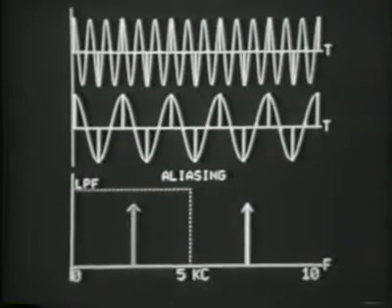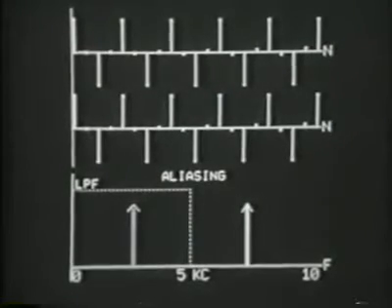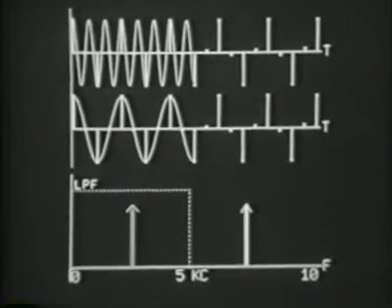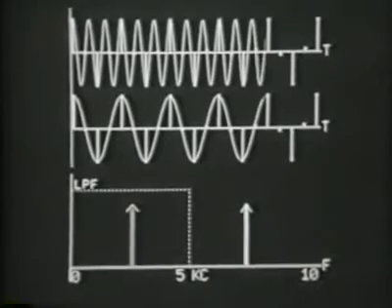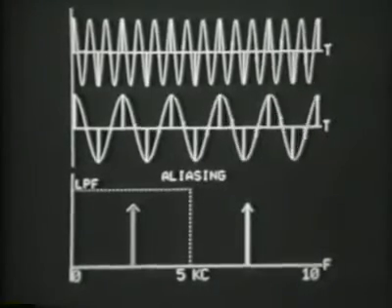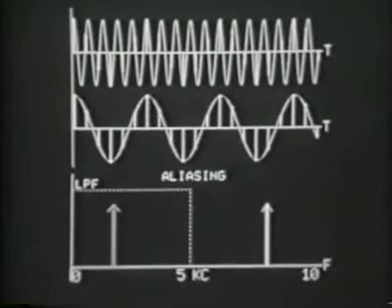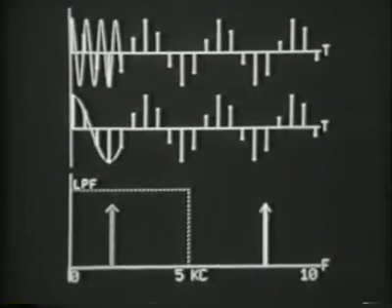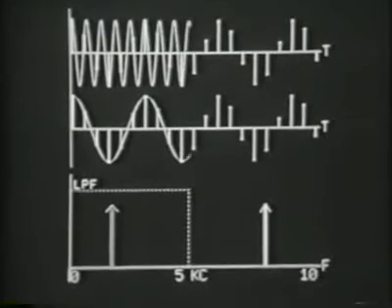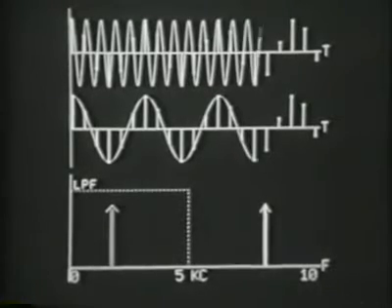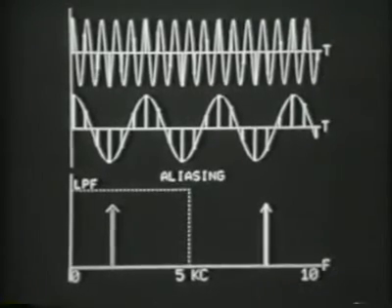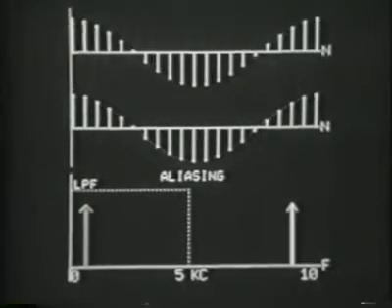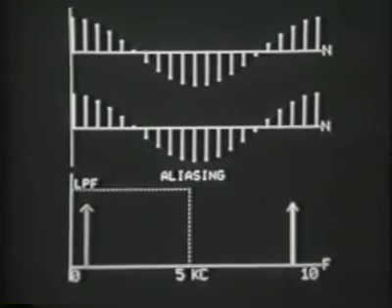But the important point is that even when we have aliasing, the samples of the reconstructed waveform are identical to the samples of the original waveform. And notice that as the input frequency increases, in fact, the interpolated output, the reconstructed output, has decreased in frequency. Now, as the input frequency begins to get closer to 10 kilohertz, in fact, your eye tends to also interpolate between the samples with a frequency that is lower than the input frequency, and that's particularly evident here.